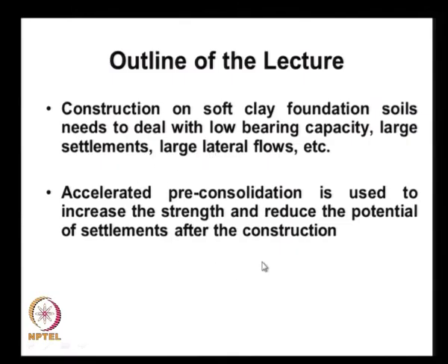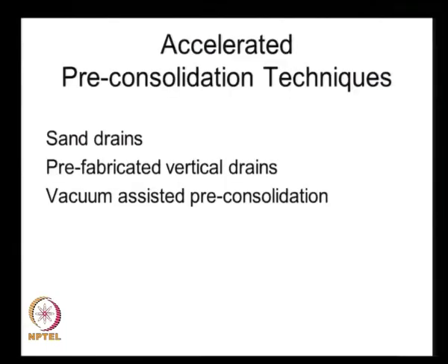Traditionally, accelerated pre-consolidation is a conventional solution used for addressing this problem, and we use it not only to increase the strength of the foundation soil, but also to reduce the potential settlements after the construction work is completed. And the use of geosynthetics has improved these techniques a lot.